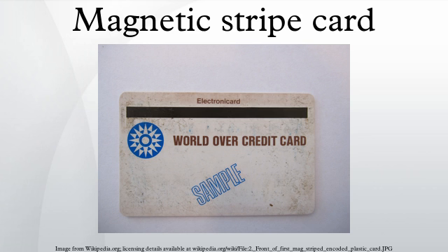Magnetic stripe coercivity. Magstripes come in 2 main varieties, high coercivity at 4000 Oe and low coercivity at 300 Oe, but it is not infrequent to have intermediate values at 2750 Oe. High coercivity magstripes require a higher amount of magnetic energy to encode, and therefore are harder to erase. High-co stripes are appropriate for cards that are frequently used, such as a credit card. Low coercivity magstripes require a lower amount of magnetic energy to record, and hence the card writers are much cheaper than machines which are capable of recording high coercivity magstripes. However, low-co cards are much easier to erase and have a shorter lifespan.